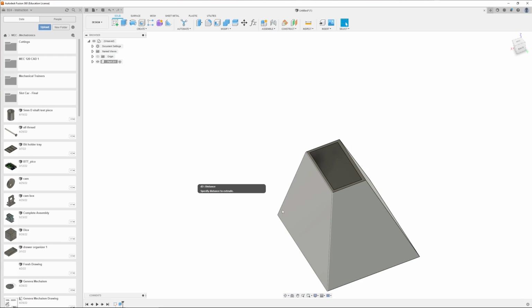And so that's one thing to keep in mind versus thin extrude or the shell operation. The shell operation will allow you to keep the object fully enclosed, or to selectively keep or remove faces of the object. We'll get into that in another tutorial when we go more in depth into the shell tool.